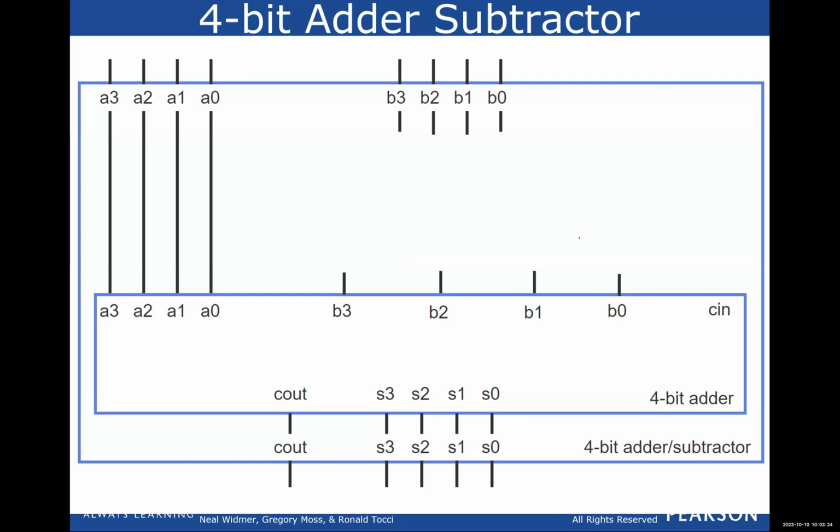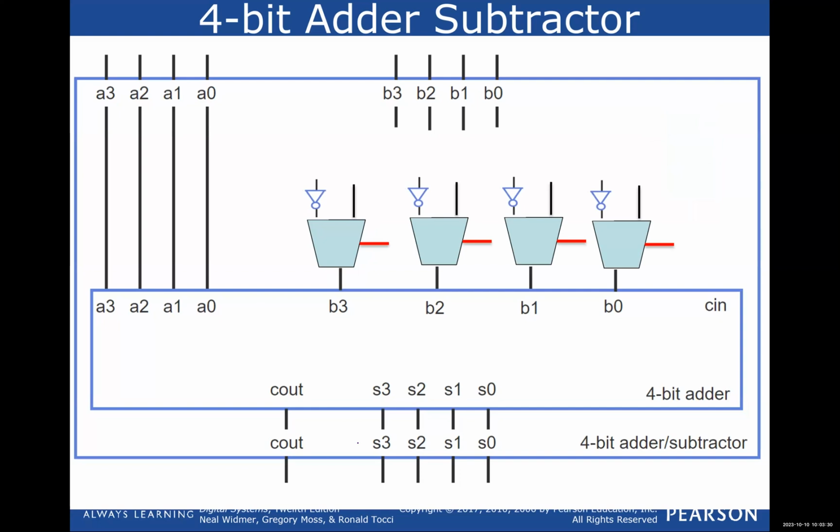And inside here, we're going to put multiplexers. Okay, this is the first multiplexer, second and third and fourth. It's going to have two inputs. One of them is to the complement. The other one is to the wire itself. And the selectors, the red ones, these are all the selectors. All the selectors here have to be connected to the same selector, right? I cannot take this one to something and the other. If I want them all to work synchronously together, I have to connect them all to the same input.